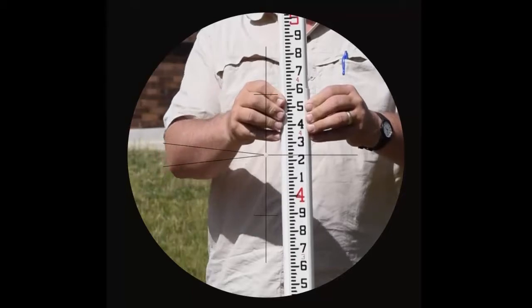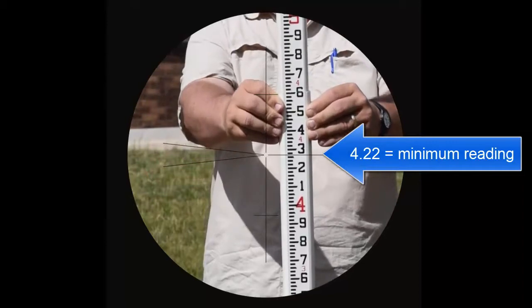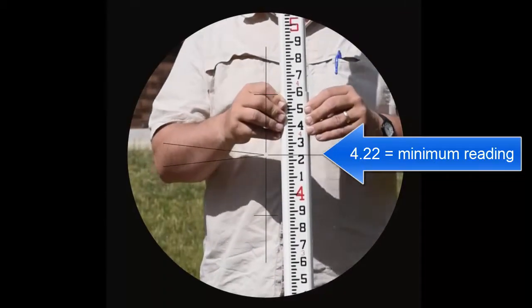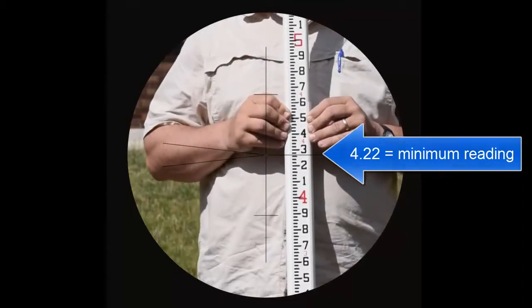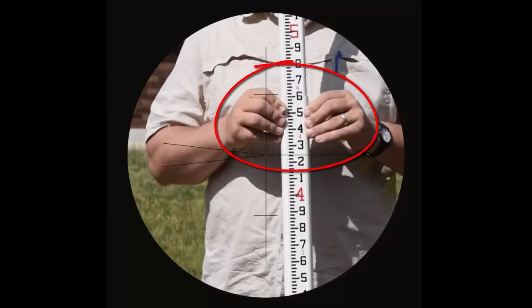To ensure the rod is vertical relative to the instrument operator's left and right, stand behind the rod looking toward the instrument. Use your peripheral vision to search out visual clues to help you keep the rod plumb, left and right, as you rock it smoothly forward and back. Do your survey partner a favor. Grip the rod by its sides to prevent your fingers from obstructing the readings. These methods are designed to minimize errors, but it is impossible to completely eliminate measurement errors.